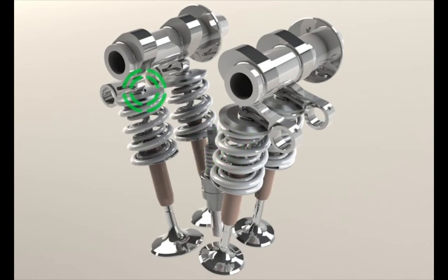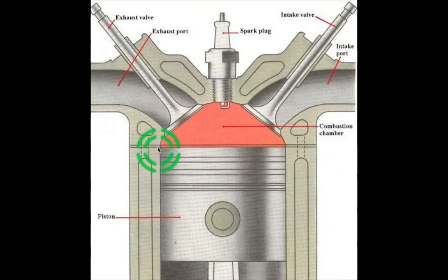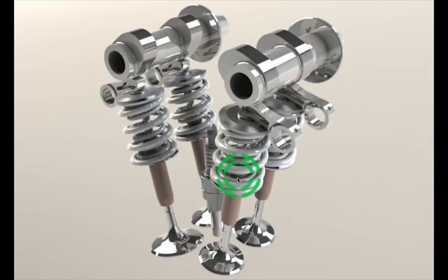And obviously this is the valve. We saw it till here, right? Now above the valve, this is how it is. Remember the springs that I was talking about? This is spring loaded like that, which is hard springs, though you can push it with your hands just like that. And you have this camshaft on top of it. This is just a cut view of one cylinder.